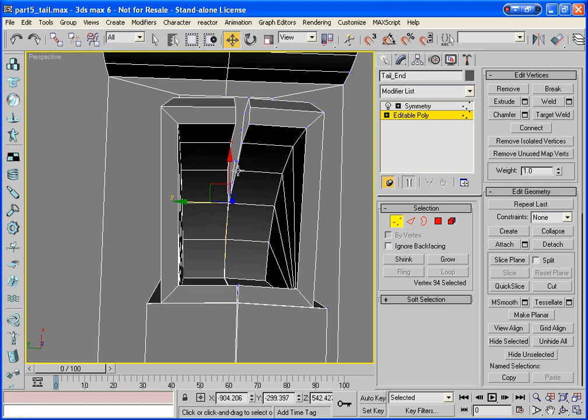Don't be tempted to use a cap. You can border it, and you could click cap, and then you would sit crying for the next however long, when you realise a couple of steps down the road, once you're well past using your undo modifier, that you have in fact ruined your entire model, and you're going to have to redo the tail again from the last time you saved.